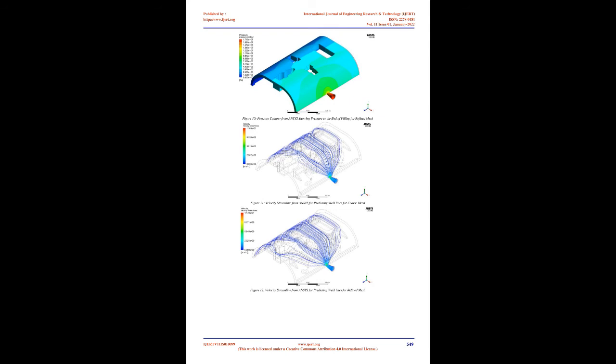The inner center gate has the advantage of leaving no visible mark in the molding as the injection point is internal to the product. However, it would be difficult to design and machine as it may require a tunneled runner system. The outer center gate would be much easier to design and manufacture, and this is the location of choice for this study. Moldflow Insight study was carried out with a coarse and more refined mesh to obtain more granular information about the flow within the cavity and also ascertain the effect of mesh refinement on the accuracy of the solution. Figure 7 and Figure 8 show the results for the initial and refined mesh respectively for fill time, injection pressure, average velocity at sampled point, and pressure at end of fill.